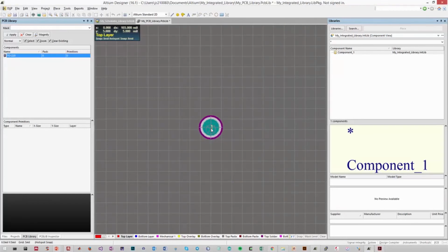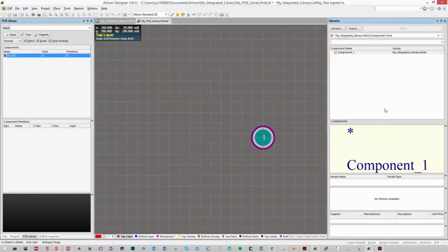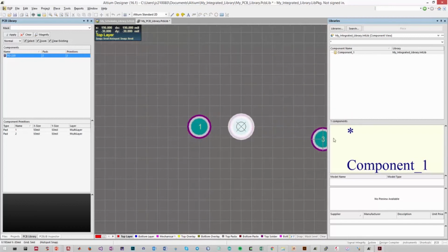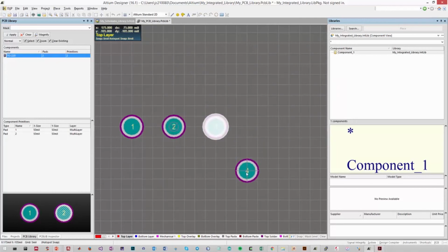So we press OK. Now we need to make sure that our gate pin is actually in the correct orientation. Is it on the left, is it in the middle, or is it in the right? So I know from looking at our drawing earlier that the gate pin is the leftmost pin when the transistor was lying on its back. And we need a pitch spacing of 100 mils. So when I'm placing this, I want to look at the XY coordinates at the very bottom left of Altium. And I want to place this on the origin, but 100 mils to the left. So right about there. So there's my pin 1. Now pin 2 is our drain, and I need to place that at the origin. Then finally pin 3, which is 100 mils to the right.